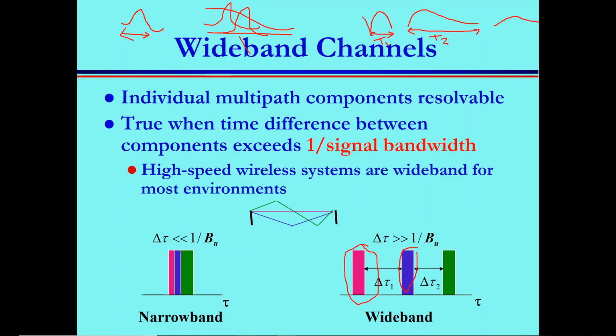So if you are sending your signals back to back, what will happen to the signals? They will interfere with each other. And this interference prevents you from being able to recover your data successfully. We need to avoid that. We need to bring new mechanisms, new techniques. And the inter-symbol interference happens not only because of the channel, but also because you want to transmit your data with high speed. You want high-speed internet. High-speed internet requires you to send symbols back to back very quickly.